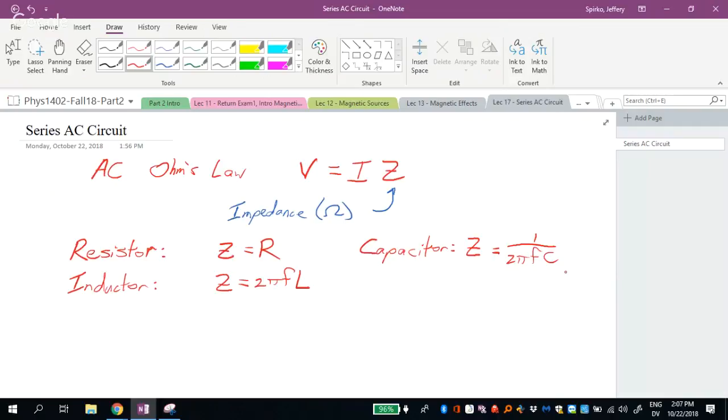One is locked in place, rigidly connected, and the other is on a long arm. When you move around, the locked one moves first, and the one on the long arm has a little bit of a delay because it's hanging out in space. So when the fins overlap or unoverlap, it changes the capacitance, and then the microchip measures that.